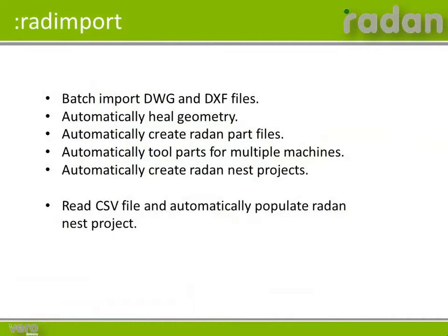Some of the highlights of Radimport are its ability to import DWG and DXF files, to automatically heal and tidy this geometry, and then from this geometry automatically create Radan part files. Now in turn, these parts can be automatically tooled for multiple machine tools, and then a nest project can be automatically created from these particular part files.